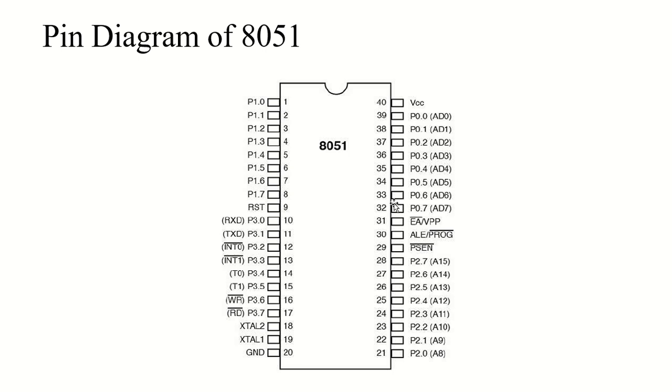Open drain is a term used for MOS chips, and we use them in the same way that we use open collector. What is open collector used for? Open collector is used for TTL chips. So in any system we are using, be it 8051 or 8052 chips, we normally connect P0 to pull-up resistors. By connecting them, we take advantage of port 0 for both input and output.